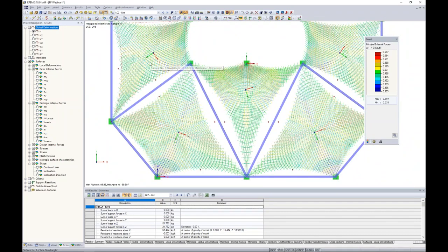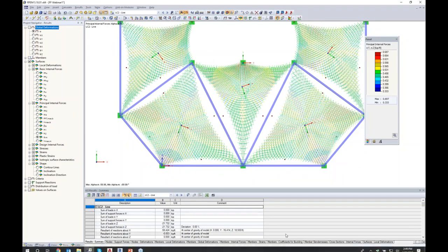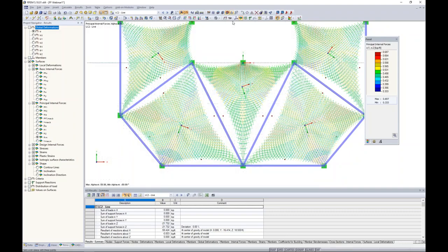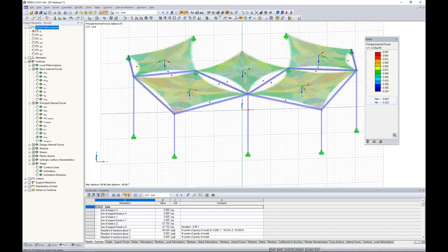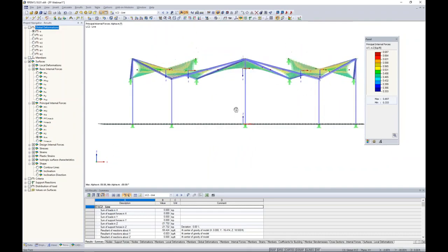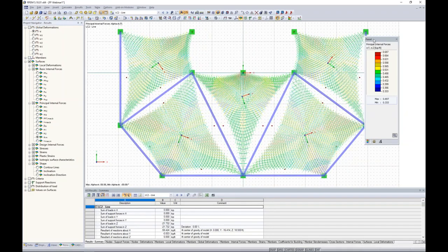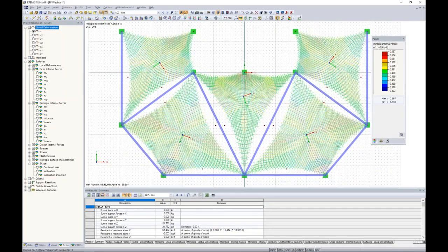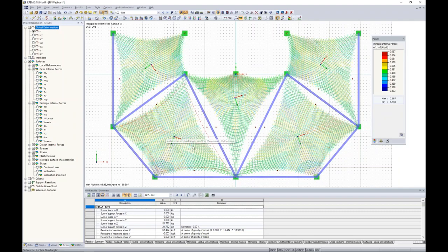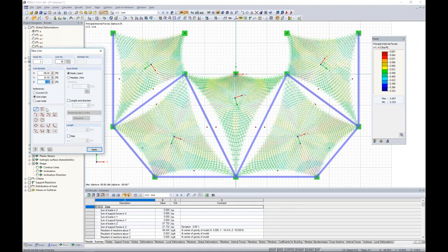So how do we orient the local axes of these members to make sure that they're taking the high tensile forces? I'm going to turn back on my grid down at the bottom, and uncheck the option for my user-defined grid, and we change this in the XY plane. So now we're just looking at that drawing grid at the bottom of our structure. We probably want to take a screenshot here, or maybe we can just approximately remember which way these high tensile forces are spanning, because once we draw a new line element, which is what I'm about to do, the program's going to suggest that I have to clear my results in order to change any type of the geometry within the model. That's not a problem.